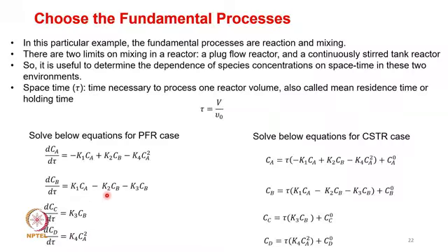Considering that that's the second order process, so now we will be able to rewrite the entire equation in the CSTR case. For the CSTR case, we have seen that this part is of course the rate of the reaction. So we see that (Ca minus Ca naught) by tau is equal to the rate of the process. So Ca minus Ca naught, let me write: Ca is equal to tau times the rate plus Ca naught.